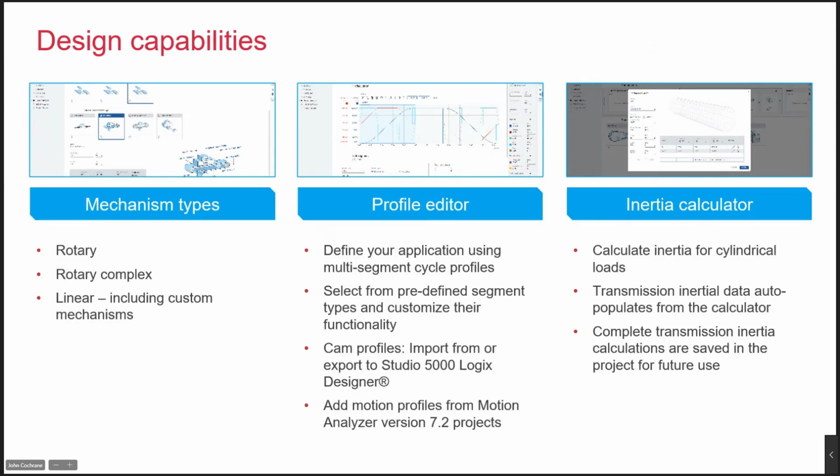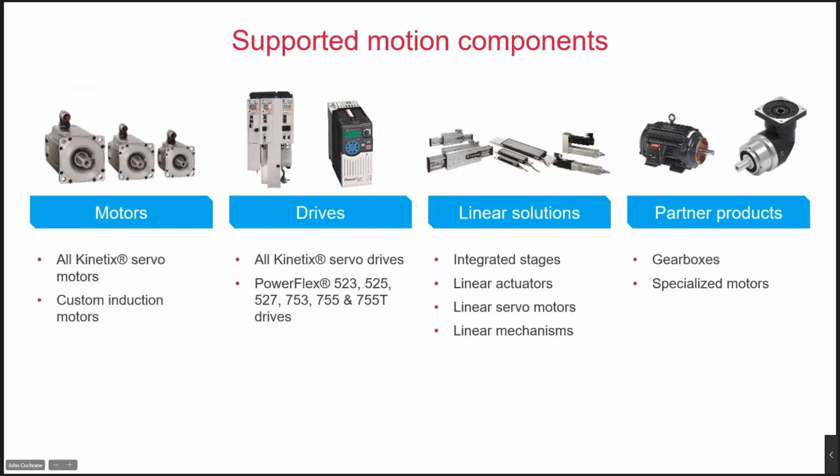And then from there, we also have some tools that are involved with this as well. One is the inertia calculator. In a lot of cases, we may not know what the inertia is of a particular component. So there is a calculator built in so that we can go in and calculate what the inertia is of, say, a ball screw or a pulley, and understand what the inertia is, which is important for the servo sizing aspect of it as well.